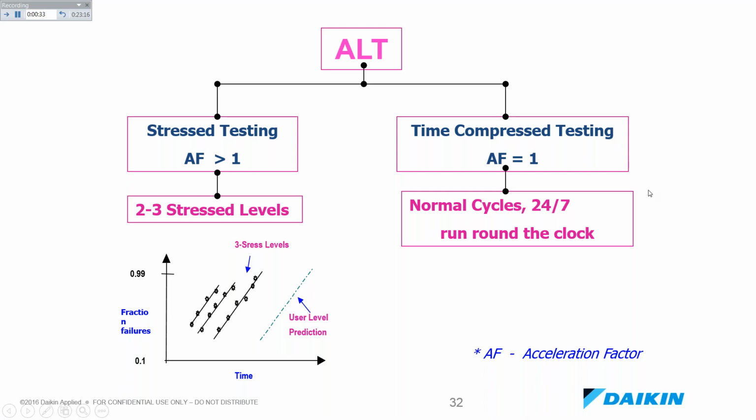So in fact, the start stop is the killing factor. So you probably want to count the number of start stops, and that's just time compression. Another example, you'll be running your vehicle like 1 hour a day. If your vehicle is run at the same condition 24 hours a day, that is like 1 to 24 time compression.